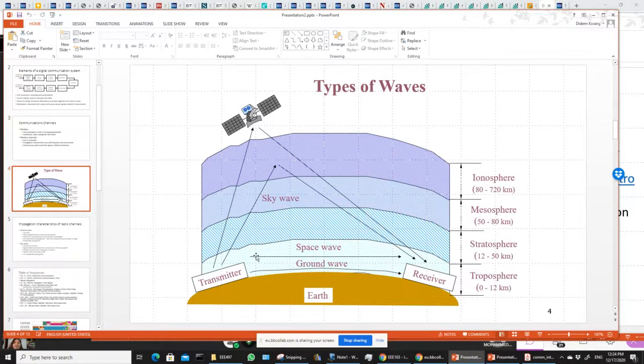Okay, so when you're transmitting, most of the communications we look at really are space waves. Although technically, there are things called ground waves, which propagate close to the ground. And you can see that the way they've drawn it, they show how it's bending with the curvature of the Earth a little bit. And that allows you to go a distance, because most transmission is limited by the curvature of the Earth. If your transmitter is on this end and your receiver is on this end, it will have to go through the Earth to get to the receiver. That's not going to happen, right? That's all rock. It will block any kind of electromagnetic signal. It's difficult to get a signal even through water, right?